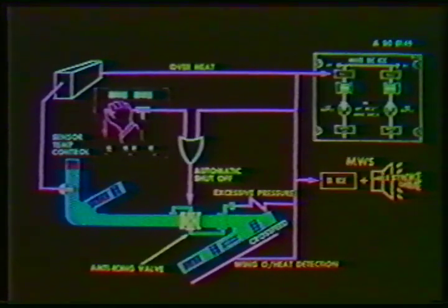Remember that the valve closes automatically when an overpressure, overtemperature, or wing overheat occurs. Pulling the corresponding fire handle also closes the valve.